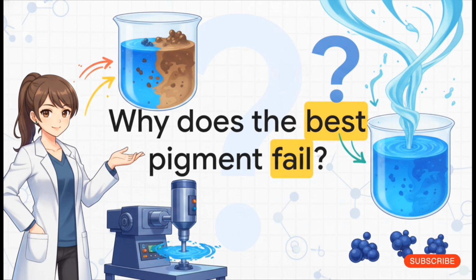Well, human nature is to immediately blame the pigment selection. But actually, the vast majority of color matching failures in our industry come straight down to poor dispersion. It is not the pigment itself, it's how it's being handled in the melt.